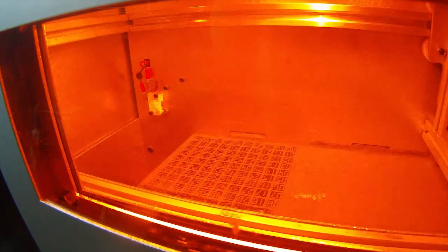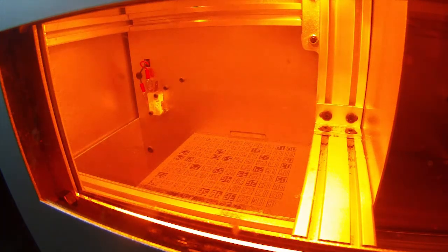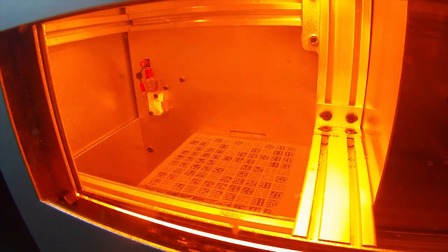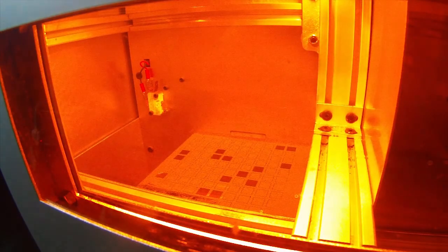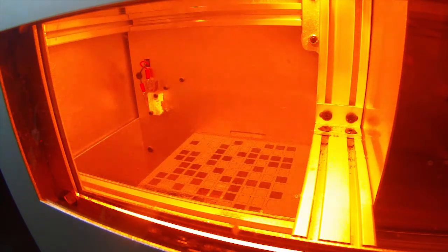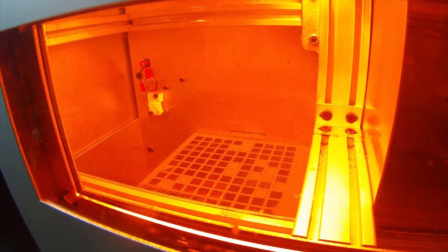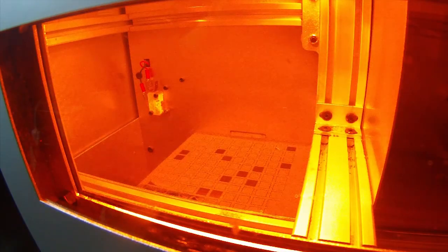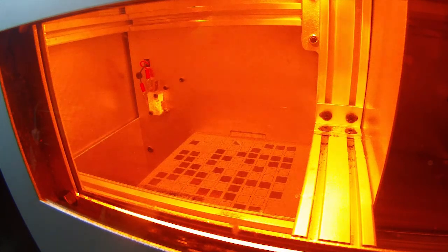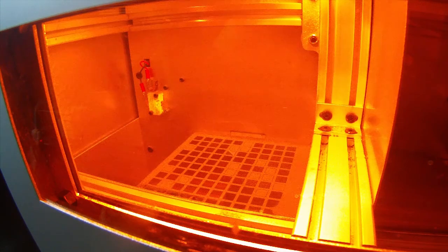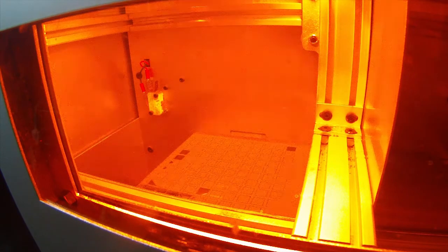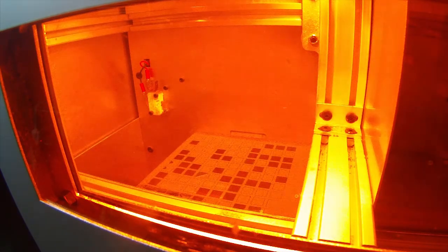So after a bit longer, I think right about now, because I still had issues, I adjusted it even more. So I moved it up to 173.2 degrees, and still continued with a 550 laser speed because I still had curling on the corners, and that helped. You can see right there, there was no plowing on that last row, and it allowed for the layers to catch up. So every time it puts more powder on, it's filling that channel on the front side.